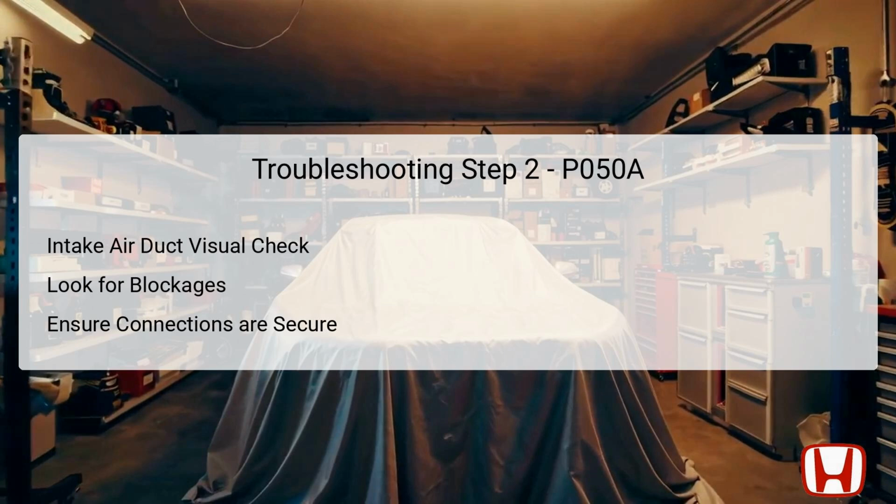Additionally, inspect the connections to ensure that they are secure and tight to prevent air from escaping. If any issues are found, take corrective actions such as reconnecting, repairing, or replacing the duct as necessary. If everything checks out, proceed to the next step.